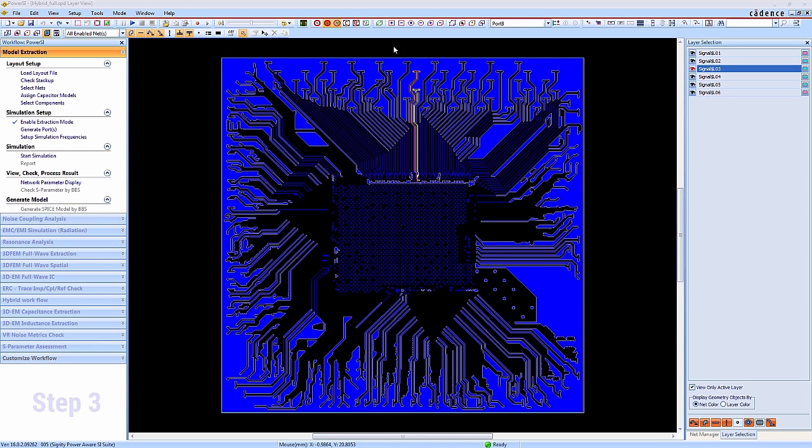We're now at step 3 in our multi-solver simulation flow, hybrid solver local simulation of the cut design. To start with, I'll cut the design quickly with a simple rectangle. We can worry later about crafting just the right 3D simulation region. First, we want to assure we aren't ignoring any PDN resonances or cutting away too much of the design for our local simulation.